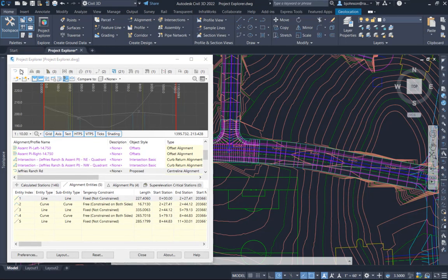One of the highlights of Project Explorer is that it gives us the ability to manage and edit Civil 3D objects within the application. Object parameters displayed in a color and with a white background on the object or sub-object panes can be edited by double-clicking on that parameter. Any change to a parameter's value is immediate and can be seen in the Project Explorer and in Civil 3D directly.